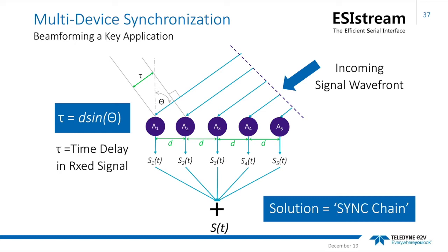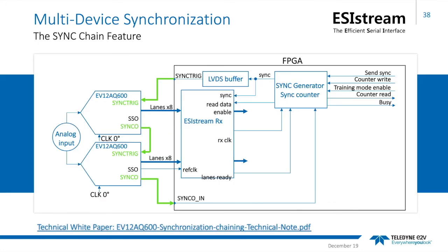So to minimize phase errors in signal sampling, it's critical that every individual channel is phase locked to a known reference. This is synchronization in action. In practice, multi-device synchronization for many systems is a major challenge. It complicates clock design and distribution. In particular, it may make designing printed circuit boards painful, especially as differential trace links need to be matched.